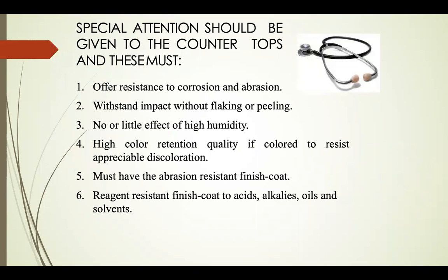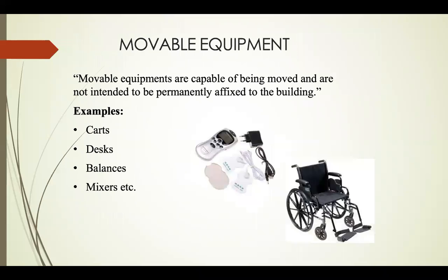Special attention should be given to countertops, and these must offer resistance to corrosion and abrasion, withstand impacts without flaking or peeling, have little effect from high humidity, have high color retention to resist discoloration, and have an abrasion-resistant finish coat resistant to acids, alkalis, oils, and solvents.